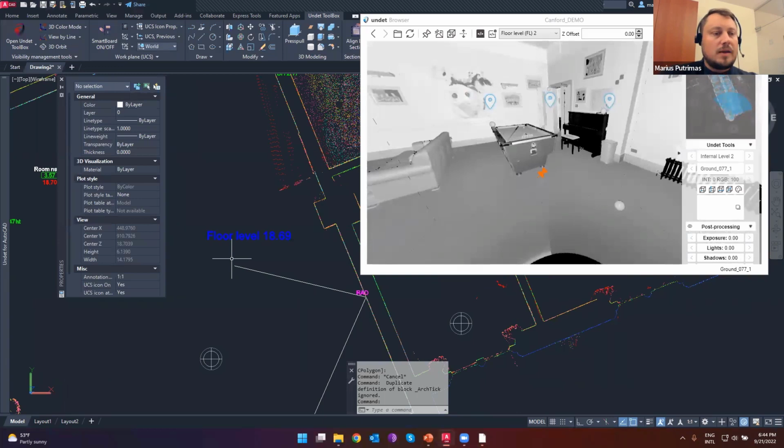So when you are customizing these block scripts, you should always purge the same existing block from the DWG file, or you just simply need to open a new empty drawing file.